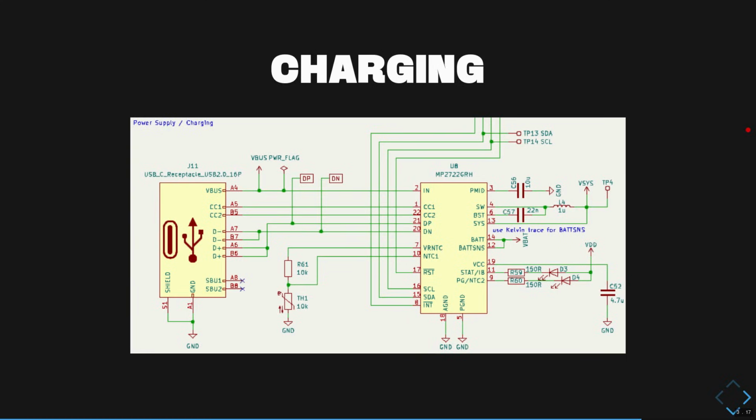And there are integrated circuits for that. A couple of them. I used one by Monolithic Power Systems, and that works quite smoothly. Another improvement would have been to use power delivery, where basically this chip or chips would talk to the PC and negotiate another voltage or higher currents than 3 amps. But that's, I would say, not necessary for this single cell charging.